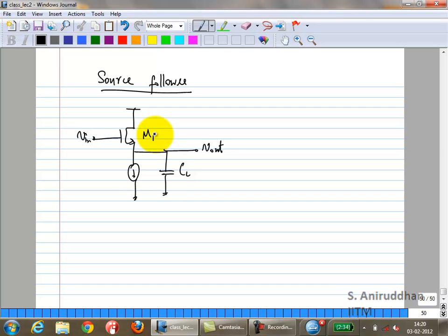How many poles do you have? How many zeros do you have? What do you think their values are going to be? Input resistance is 0. So assume it's driven by an ideal voltage source. You only have one pole at the output, right? What is the pole frequency?